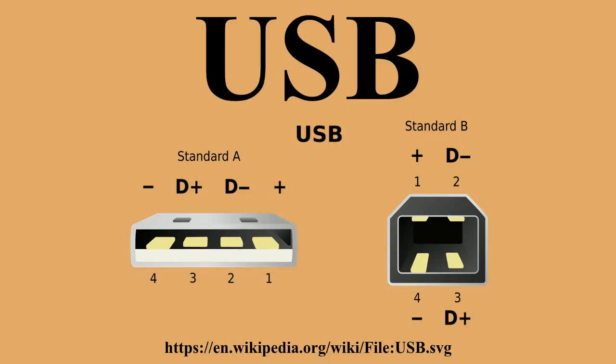For mice and keyboards with dual protocol support, an adapter that contains no logic circuitry may be used. The hardware in the USB keyboard or mouse is designed to detect whether it is connected to a USB or PS2 port, and communicate using the appropriate protocol.